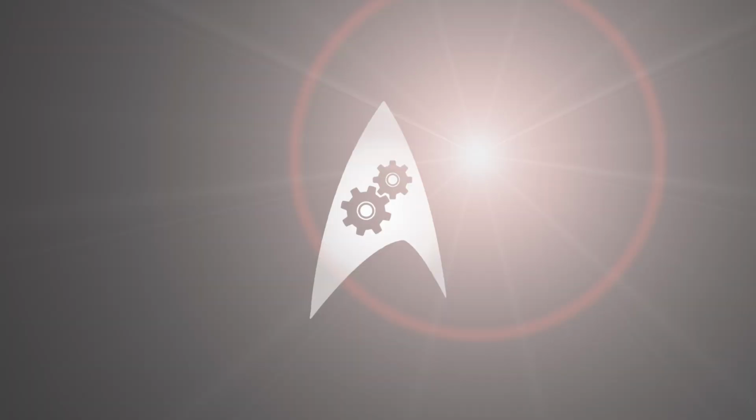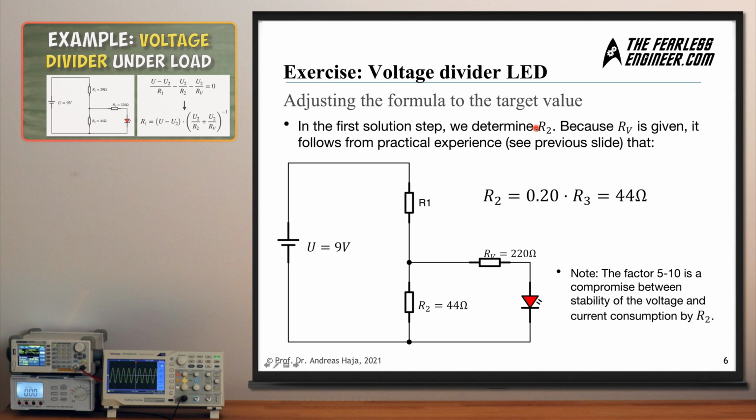Okay, now let's take a look at the first solution step here, in which we determine the value of R2. We have RV given, it's 220 ohms, and it follows from practical experience that the value of RV, or the value in the loaded branch, should be 5 to 10 times larger than in the voltage divider branch. And as stated on the task slide, the factor is 5, which we are going to take here in this case. So since we know that RV is 220 ohms, we now multiply RV, or R3 as it's called here, with a factor of 0.2, which renders R2 to a value of 44 ohms. So R2 is 44 ohms in the setup.